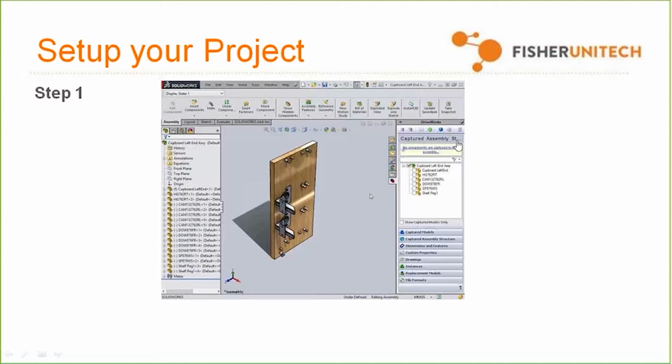Now the capture process is right over here. You can capture an entire assembly structure by clicking on every single component in that assembly, or you could just capture the top level. Depends on what your needs are. Some of the things that you can capture and control, and this is not a complete list, but you can capture control dimensions and features. So you can capture and control the size of particular designs, or whether or not a particular feature, as an example, is suppressed or unsuppressed.